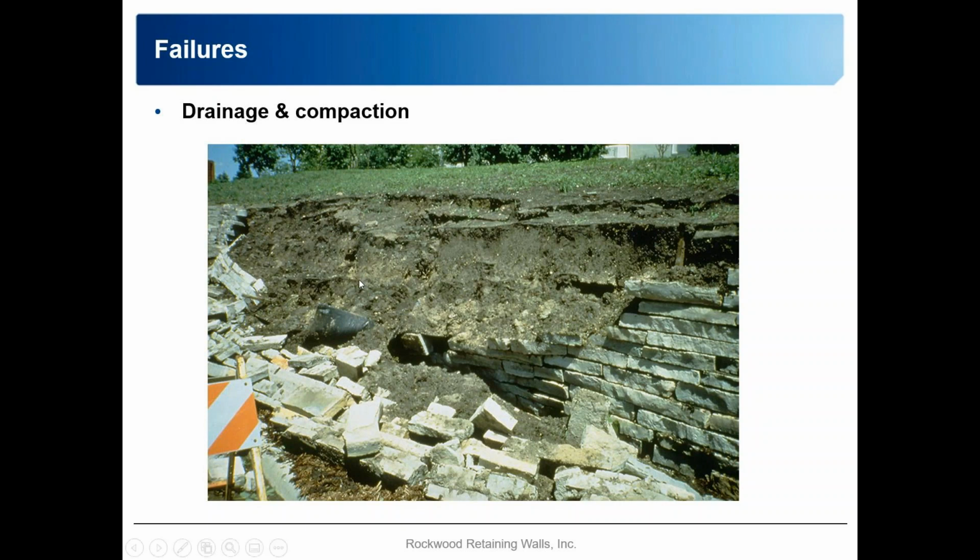directly behind the wall. So as the natural material that we're looking at here goes through freeze-thaw cycles, so moisture gets added to the soil and it goes through a freeze cycle, it just keeps moving and placing additional pressure on this wall over time until eventually it just collapses and rolls over. The other thing, again, that's a little bit less obvious is there's kind of a slight hillside here which would help divert and channel water down to the wall. So it's really a combination of poor drainage, no stone, and water being directed directly at the wall.